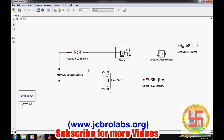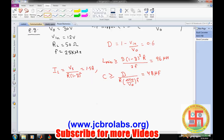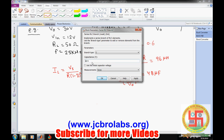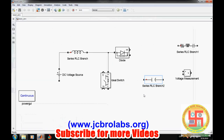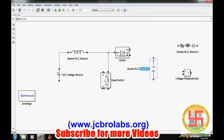This switch goes here, and then this has to be a capacitor, and the value of the capacitor is 48 microfarad. So 10⁻⁶ is already there, so we'll convert it to 48. Now let's rotate it in the clockwise direction. Change it to C only, and change it to L.